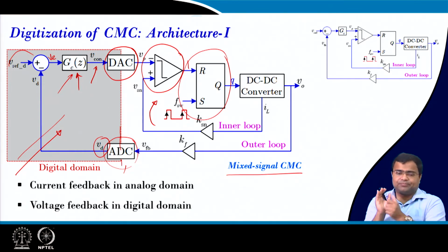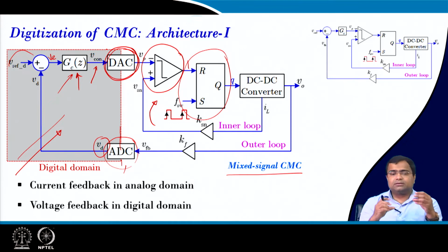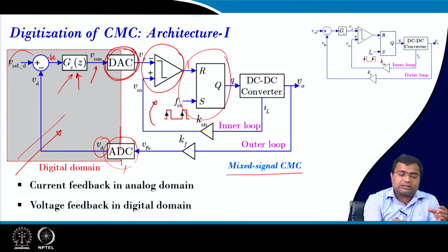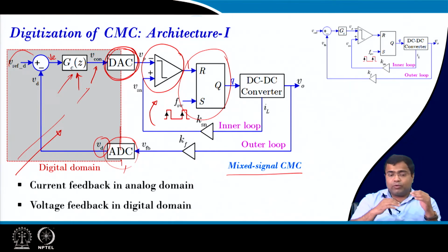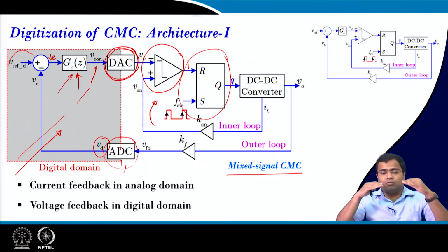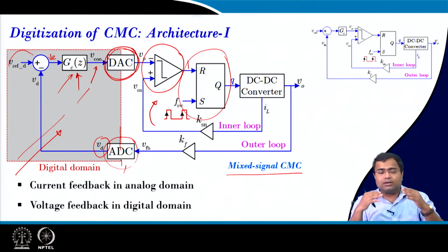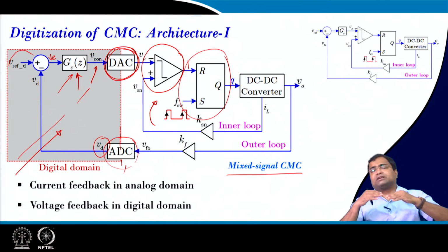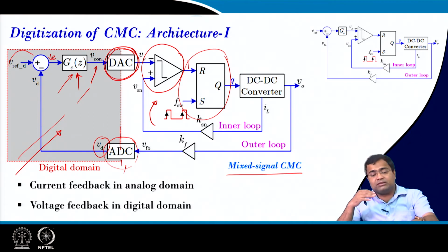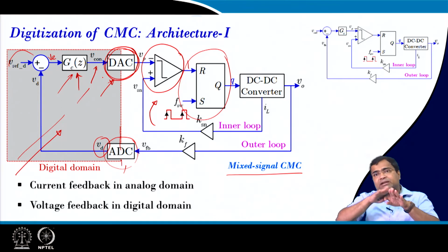That is another possibility. The third possibility, since we are generating the reference current from inside the digital controller, that means this being whole digital, we can always use a programmable current reference, because in peak current mode control we should be able to protect the circuit. That means if you want to protect, we want to program the current reference to either a higher or lower value, because if we use a programmed current value from the digital domain, then it will limit the actual inductor current.